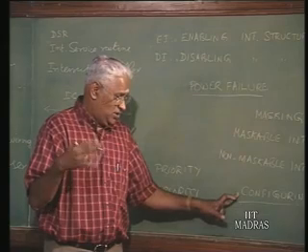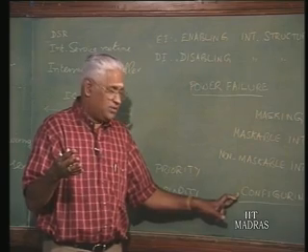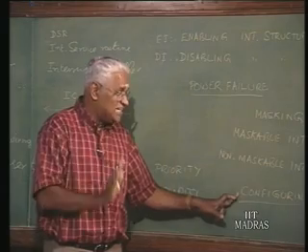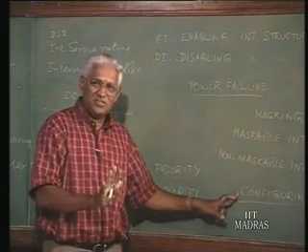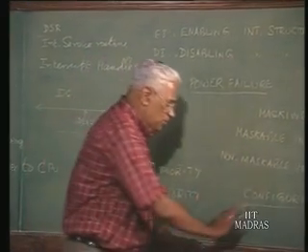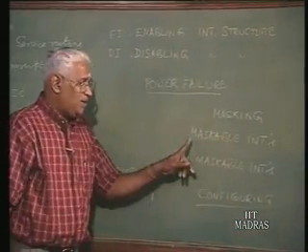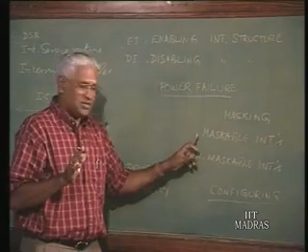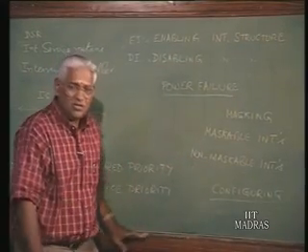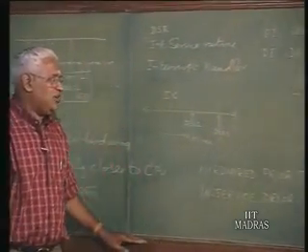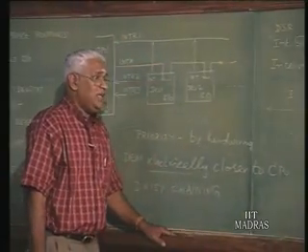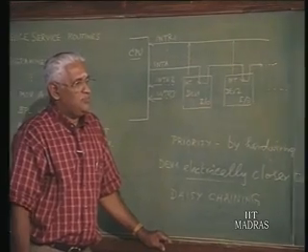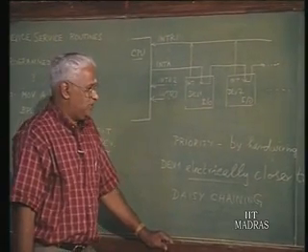Sometimes it may be so critical that even the interrupt instruction cycle may not be completed, but anyway, if it is called an interrupt, the instruction cycle must be completed. Now, during the configuration phase we may selectively mask, meaning selectively enable and disable certain interrupts. Non-maskable cannot be touched at all, and generally these non-maskable interrupts are used for very critical things such as power failure, some other system failure aspects. Good.